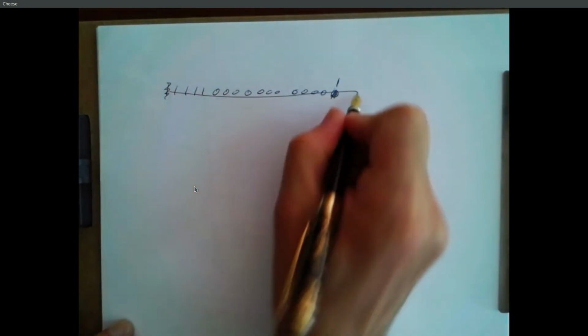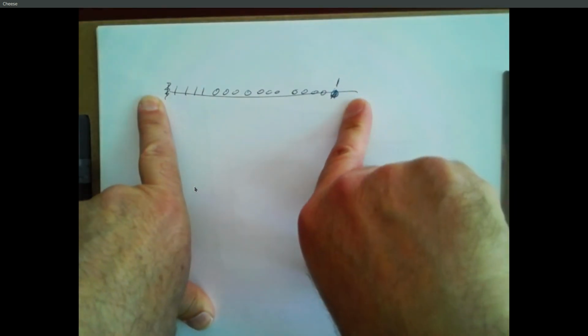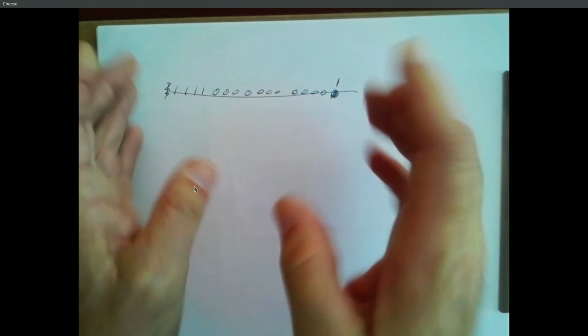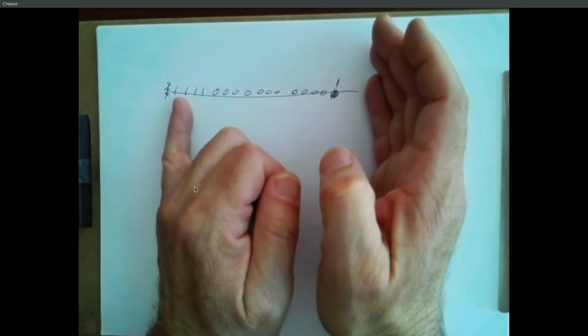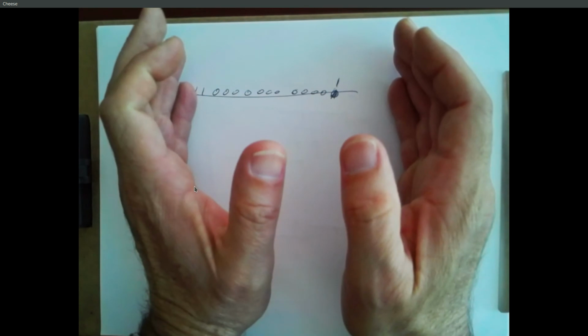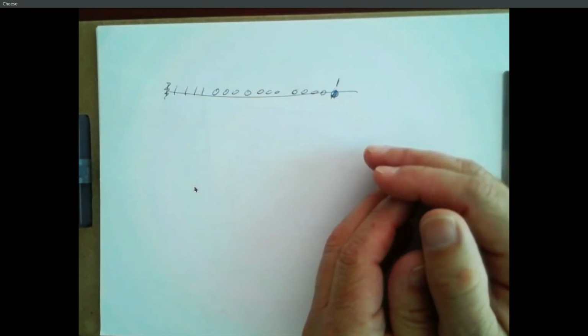But question 4, experiment 4, is building a shift register. And that's actually what you need for experiment 5, because we need to look at the last 16 values that we saw, and we need to do that in a way so that when we get the next event, we forget about that first event and just remember the last 16. That's really what a shift register will do for you.